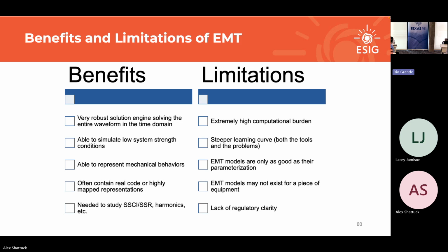The other limitation here, again, we've mentioned a bunch of times, is that the EMT models are only as good as they're parameterized to be, taking out of the context that they have to be right in the first place. Let's say we trust the OEMs to make a right model always, which might not be the case, but if they get it wrong, they'll fix it. So even if we trust the blocks being correct, wrong parameterization means wrong model. So this is the exact same limitation. One of the main limitations of the PSPD as well is we're just not using them right. Which, if you're not using it right, why would you do the study in the first place?